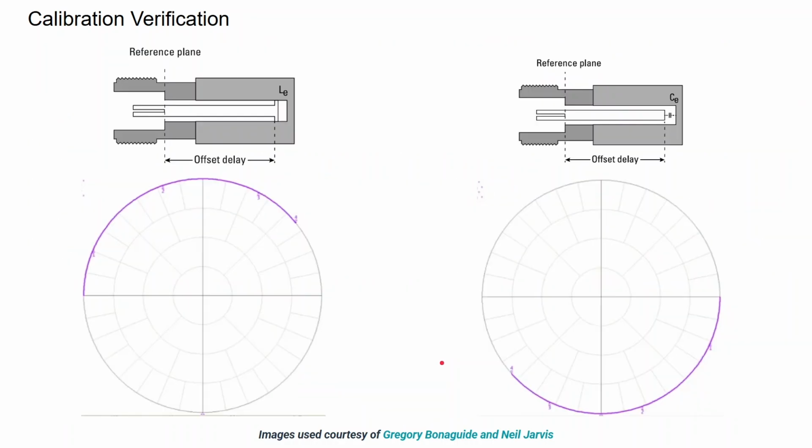So here's an illustration. These are actual traces. This is when I connect my calibrated short. Notice at the low part of my sweep, I am at 0 ohms, and as frequency goes up, here's 1 gig, here's 2 gig, here's 3 gig, that I get more and more reactance, and that's why I see this arc.